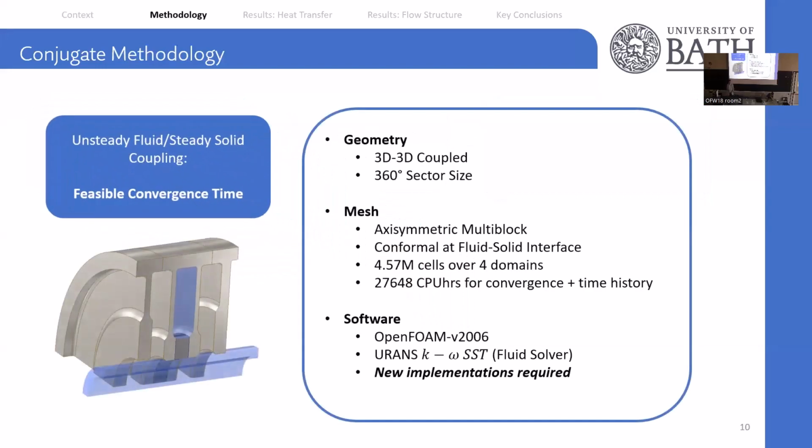So we've used a 3D coupled sector with a 360-degree sector size, and this was done to ensure that the development of the structures is not impeded by any periodic boundaries. An axisymmetric multi-block mesh has been used, which has been conformal at the fluid to solid interface with 4.6 million cells over the 4 domains and 27,000 CPU hours used for convergence.